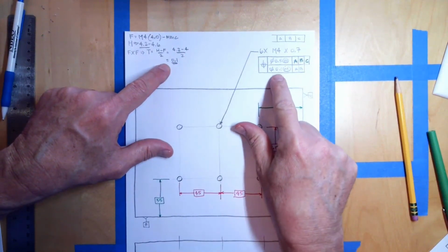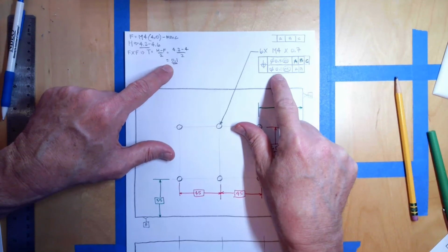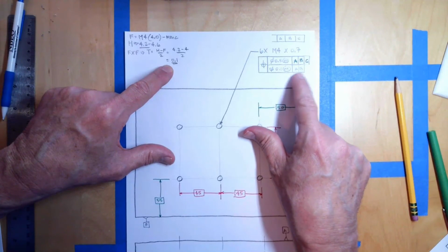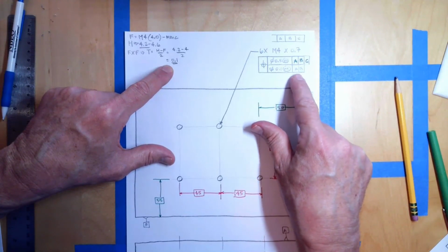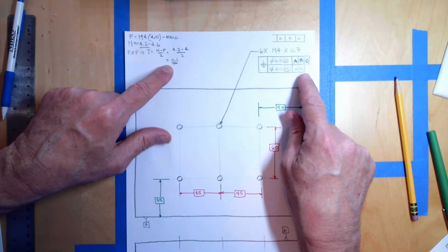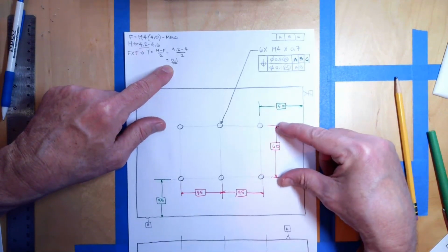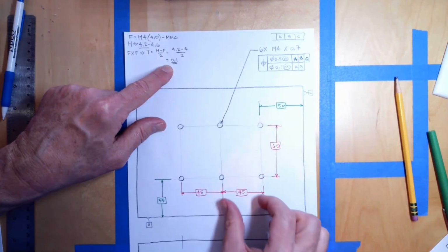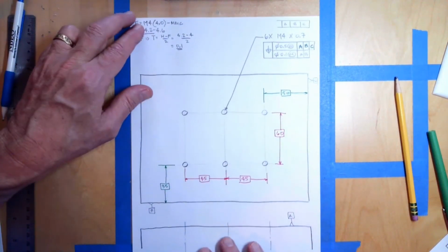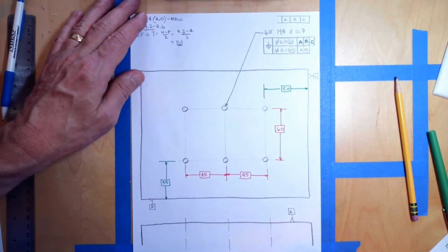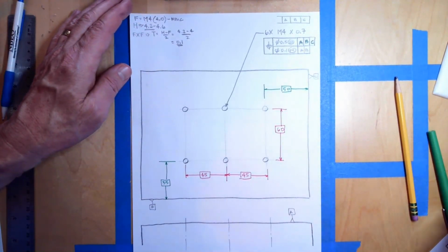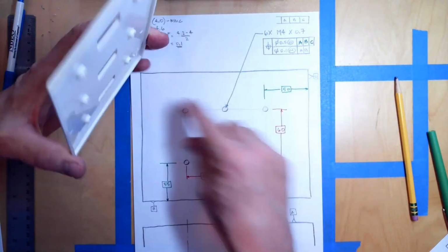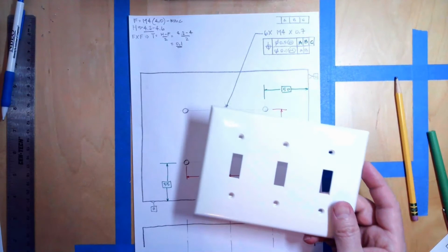That gives us a tolerance in the feature locating tolerance zone framework of 0.1 at MMC relative to A and B. So that means that A and B, it needs to be oriented relative to these datums. And the feature locating tolerance zones are basic 60 millimeters apart and 45 millimeters apart this way. And so that's the solution for this example of designing a box for this cover plate.